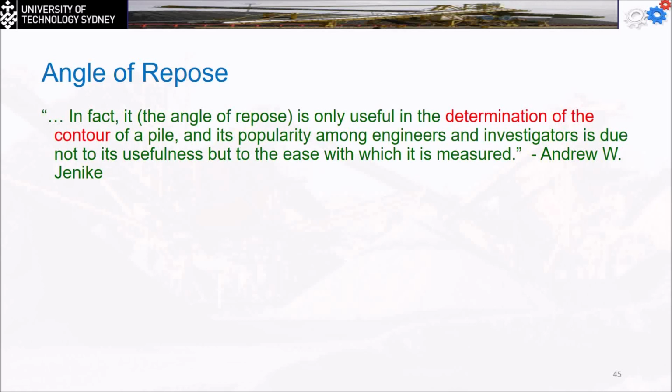So they have a cone, they fill it with the concrete, then they remove the cone and check. If the concrete slumps to a lower level, then you cannot use it. So it's something like the repose angle, but this is a repose height. It should always hold itself standing to be accepted for casting.